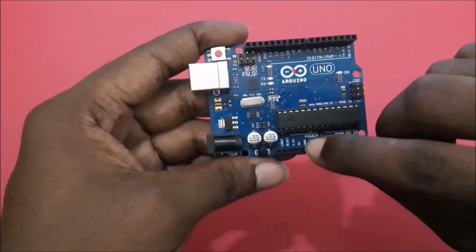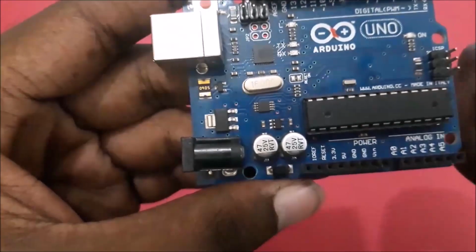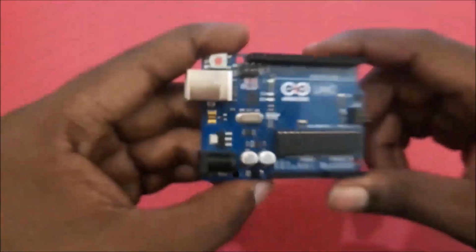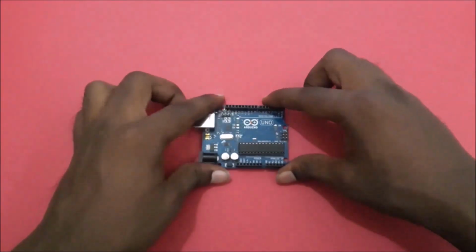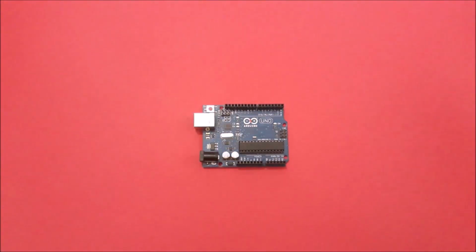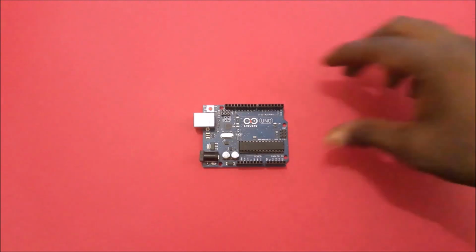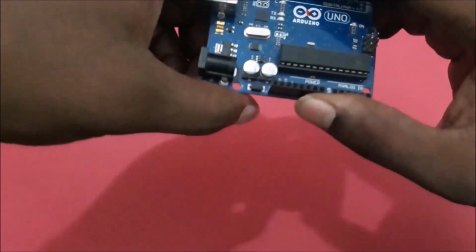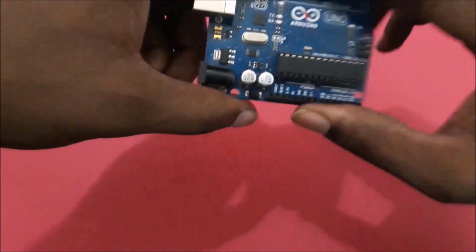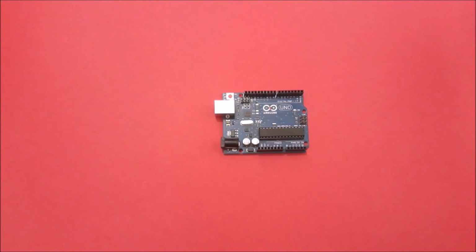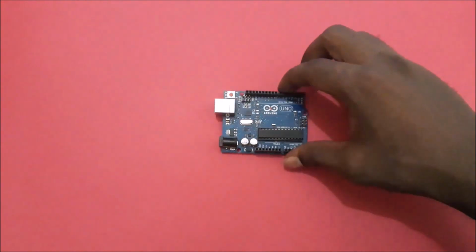And yeah, there is this 5 volts pin. If you have a close look at this, there is this 5 volts pin. This 5 volts pin is used to connect sensors and other devices which require low power. So you can connect a servo. For powering up a servo you need to connect it to 5 volts. For powering up some ultrasonic sensor or Bluetooth module you need to connect it to 5 volts, right? And there is this 3.3 volt pin as well. This is again for those devices which require very little power.